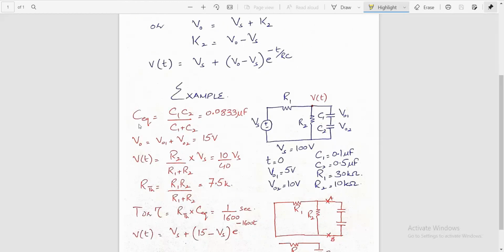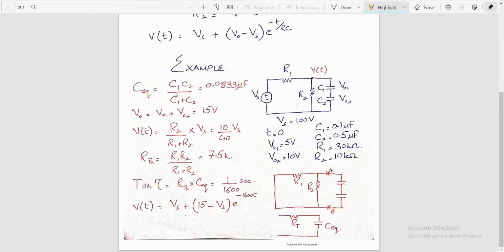You are having a linear circuit in front of you. You have a voltage source which is connected to a resistance R1, which is in turn connected to a resistance R2, and a combination of C1 and C2 through a node which I have defined as a red dot, so that you can see that this node is the point of interconnection of R1, R2 and the combination of C1 and C2. Anyhow, the voltage of this node is designated to be V of t.